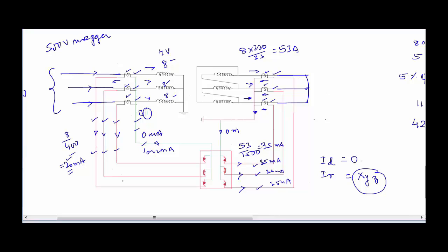So we will be performing the insulation resistance test of all these four sets of cable on the HV side of the transformers, and the same thing will be carried out on the LV side circuit as well. So we are going to remove this earthing, and we are going to perform the IR insulation resistance test of this cable, this cable, this cable, and this cable.